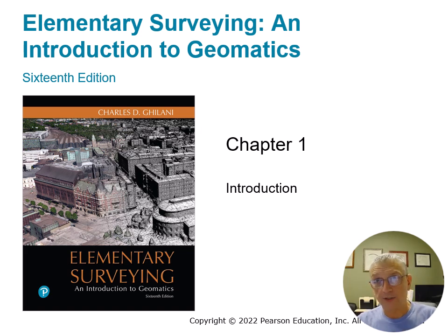Now, in the last decade or so, GPS is used more. GPS, listen to this, does not measure. GPS surveying is not measuring, it is positioning. And we'll talk about that, but that's a little bit of a mind blow maybe for some of you that's got some experiences that we don't really measure with GPS, we position. And it's two totally different approaches, equipment sets, and math to get very similar, if not hopefully identical, results.